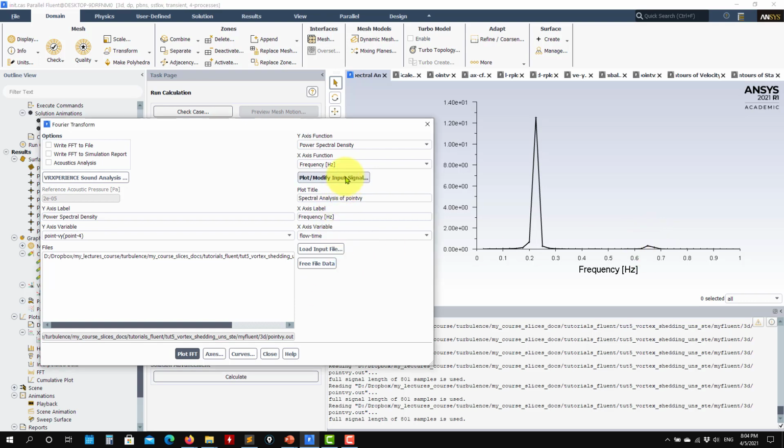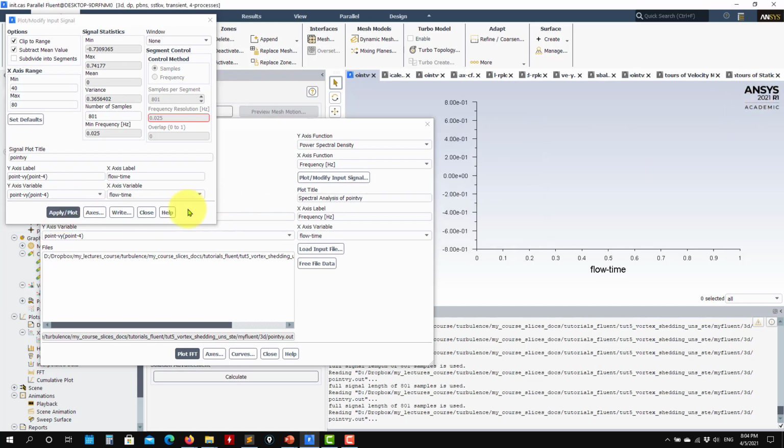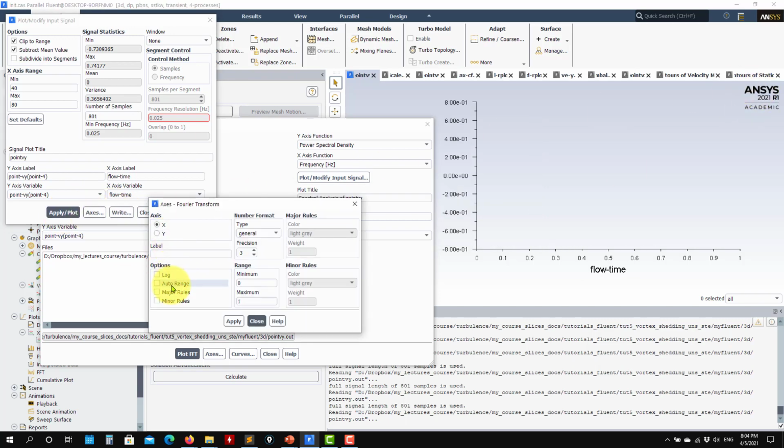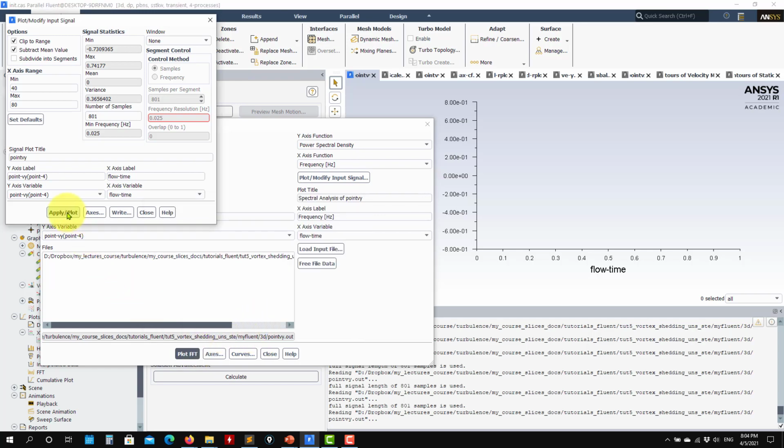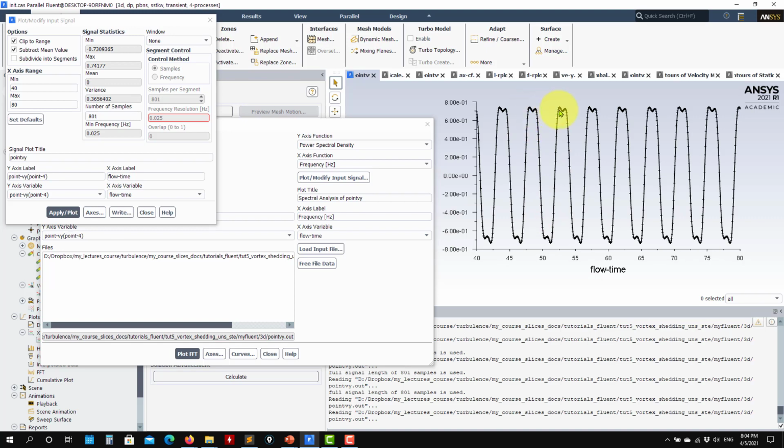So as you go back to your signal, it's clear that it will be here and here. See that you have the clear one between the large peak, but the other higher frequency is this one. Okay, so see that you can detect all those frequencies. So doing this now visually, it becomes trickier, and sometimes these signals can be very, very non-uniform. Here you see that you have kind of a periodic behavior, sometimes can be very non-uniform, so it's not straightforward to count that visually, okay? So this is the advantage of doing this kind of signal post-processing.